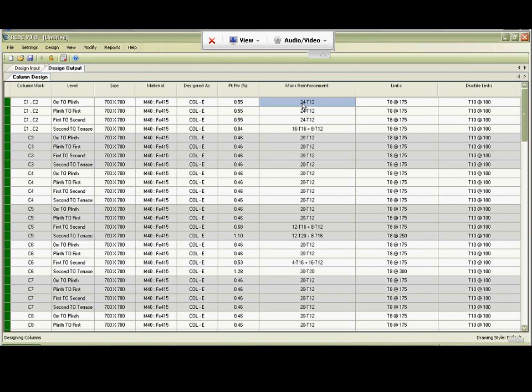For copy and paste to work, the only requirement is that the size of the column should be the same. As long as the size of the column is the same, the same arrangement can be tested to see if it works. There are a couple more quick detailing options which help you detail at a macro level.